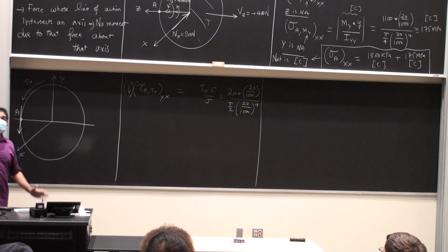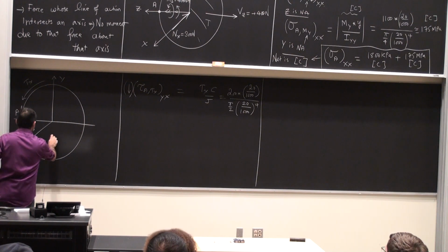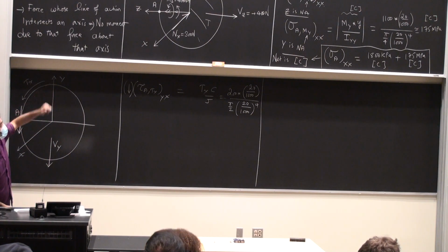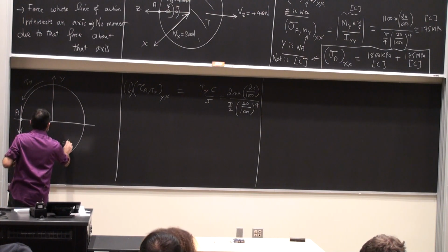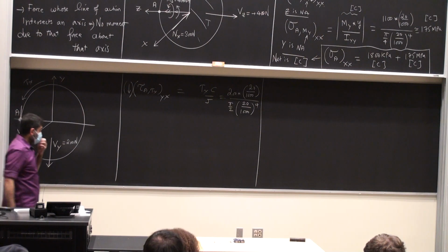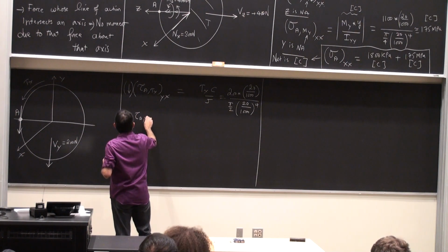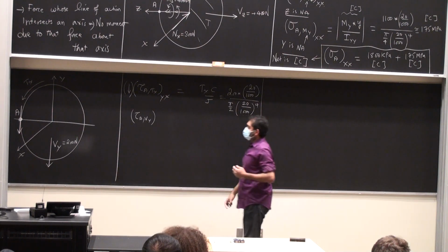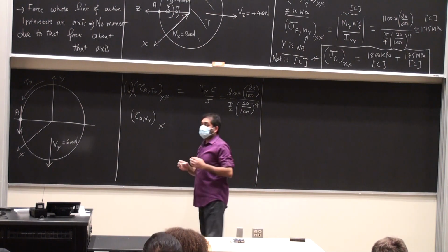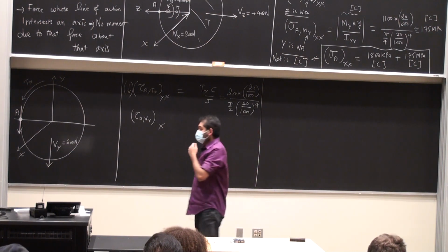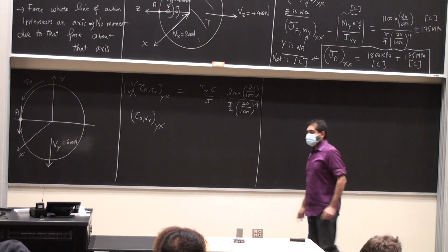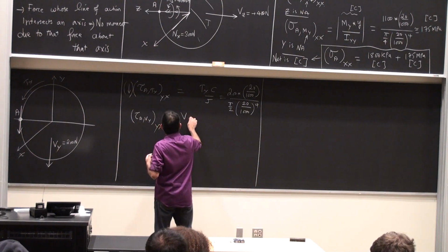Then I look at the two shear forces, Vy and Vz. I'm going to have Vy, and as you can see, E is pointing vertically down, so that's 200 newtons. Point A is sitting right there. So tau A, Vy. This is also going to have the same subscript, the Yx subscript, x being the area normal, y being the direction of the shear force which causes the shear stress. We have our formula: Vy, Q.